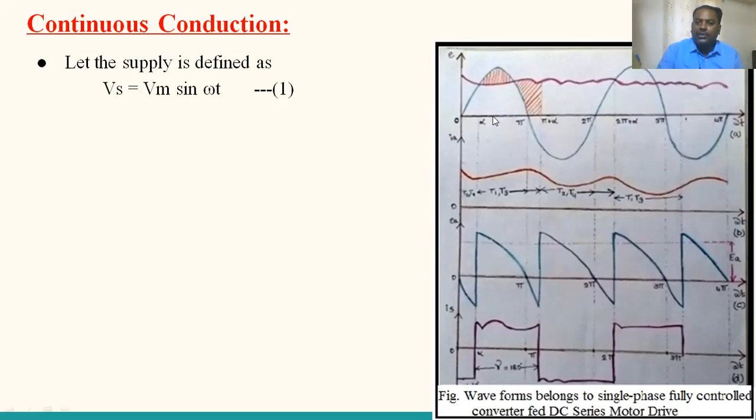During the positive half cycle, we give a triggering pulse to the two thyristors simultaneously at omega t = alpha, so that Vs = Vl. The source voltage entirely appears across the load. This process continues up to pi. At the instant of pi, the supply voltage reverses.